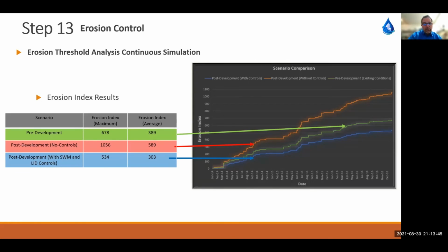In this case, they implemented stormwater management, flood control with extended detention, with sufficient storage so that most of the storms, peak flow, and other flows below the peak are reduced to quite a bit lower than post-development.